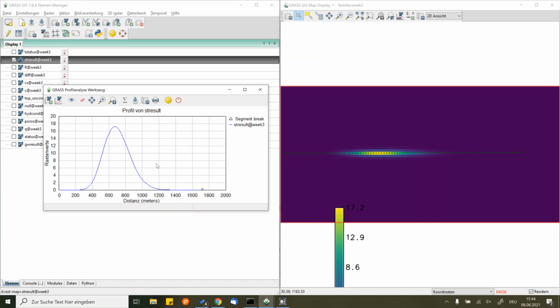So now you could start to analyze those kinds of effects by, for example, setting the groundwater flow velocity to 0, so putting the pressure head value simply to 0 with no gradient, and see what the diffusive effects then would be. Or the other way around, setting the diffusivity of the solute transport to 0 and see how much numerical diffusion you have if there is only advection taking place.